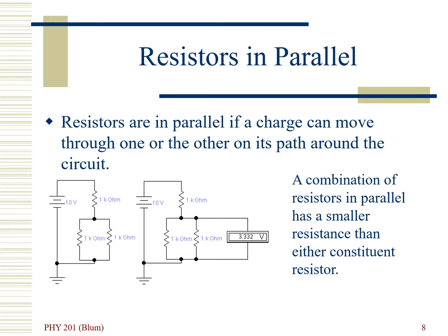In order for us to achieve the digital to analog converter, we're also going to need the concept of parallel. So here we show the first kilo ohm resistor is in series with a parallel combination. So the two lower resistors are in parallel. There's a connection of wire on the top, a connection of wire on the bottom. That's our definition of parallel. Resistors in parallel add reciprocally and end up with a smaller overall resistance.